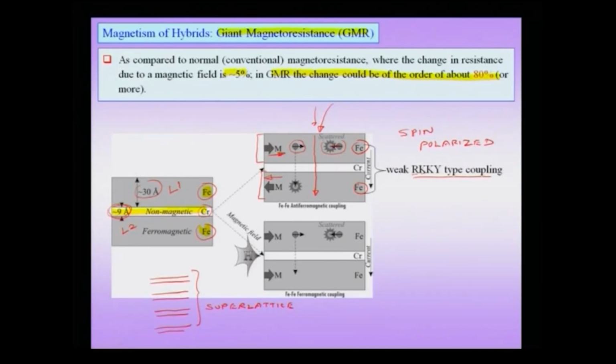That means a spin which is pointing to the left will get scattered more, as compared to an electron spin which is preferentially oriented with respect to the magnetic field. So, spins which are wrongly pointed get scattered, and if they are scattered, that contributes to resistance, and this is purely coming from spin polarization related scattering. That means it is spin related scattering and not the usual phononic or impurity kind of scattering which we have talked about before. So, this is a new kind of phenomenon.